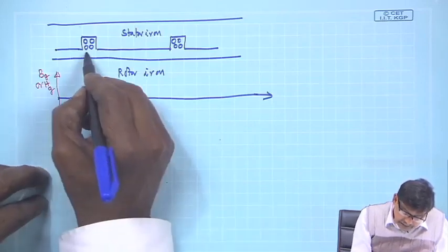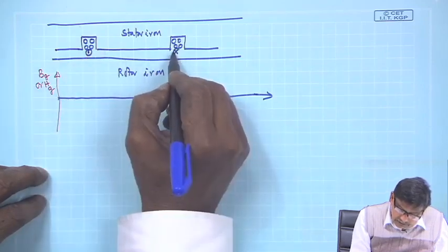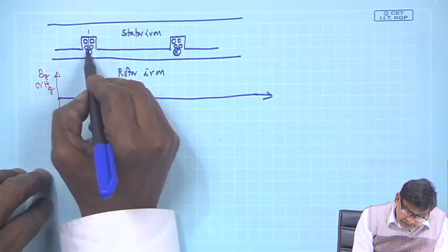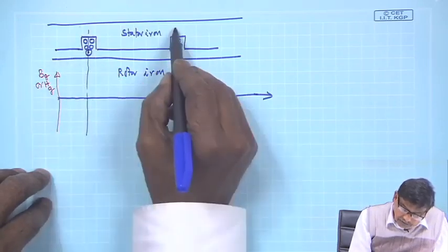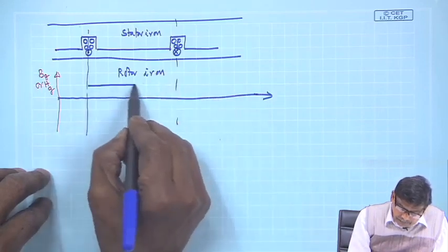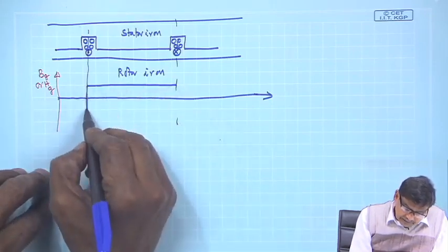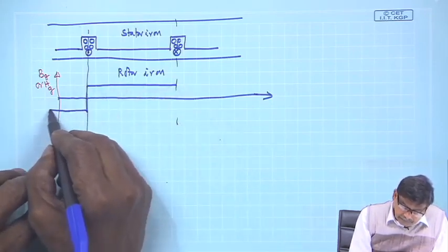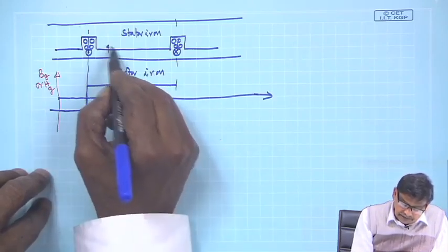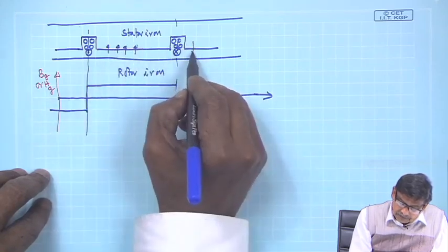Then if these conductors are carrying dot currents and these conductors are carrying cross currents, of constant magnitude, what you do is, at the center of these slots, you draw two vertical lines, and between them it will remain constant, and then it will switch over to negative sign, because lines of force here are like this, south poles, and here the lines of force will be like this.